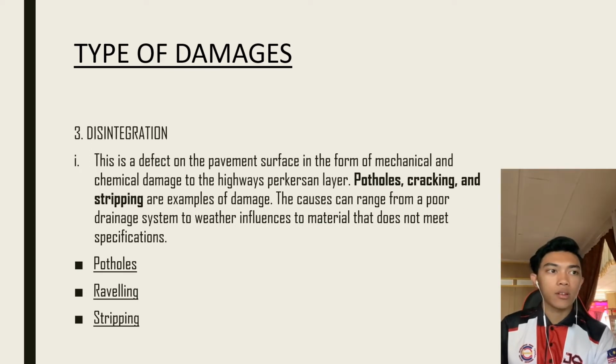A pothole is a depression in a road surface, usually asphalt pavement, where traffic has removed broken pieces of the pavement. It is usually the result of water in the underlying soil structure and traffic passing over the affected area. Water first weakens the underlying soil. Traffic then fatigues and breaks the poorly supported asphalt surface in the affected area. Continued traffic action ejects both asphalt and the underlying soil material to create a hole in the pavement.